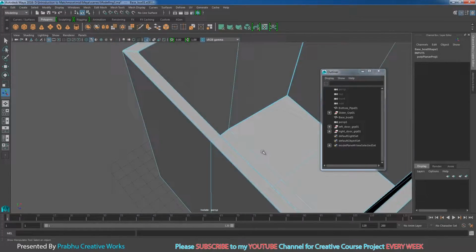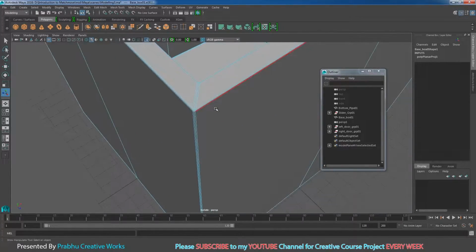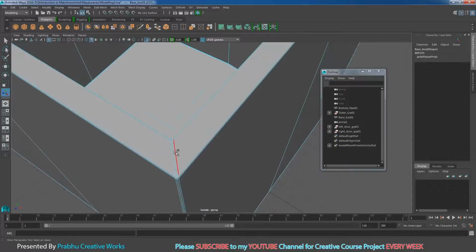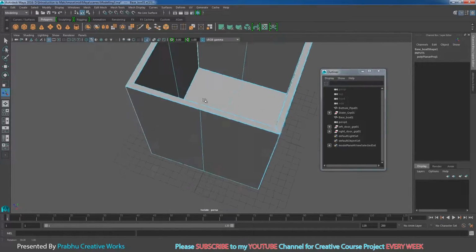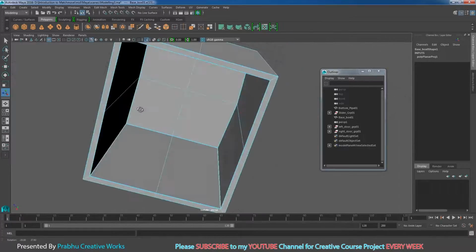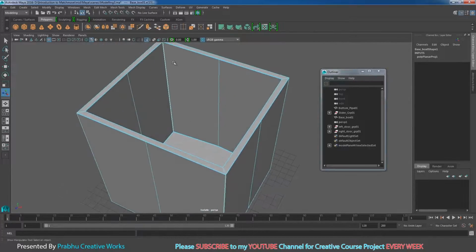Like this you want to do on all the other sides. Hold shift and double click on this corner edge, and hold shift and double click on this corner edge, and hold shift and double click on this corner edge. So our 4 corner edges will be selected with the whole loop.